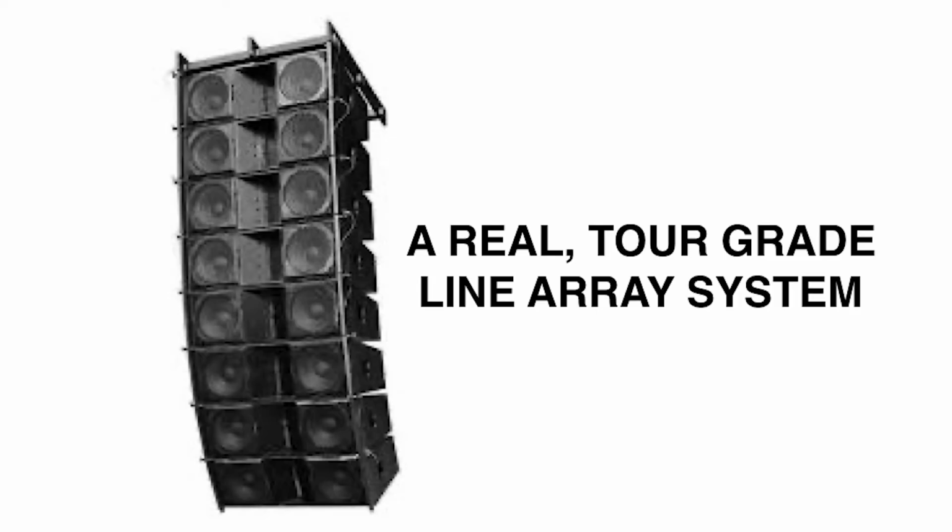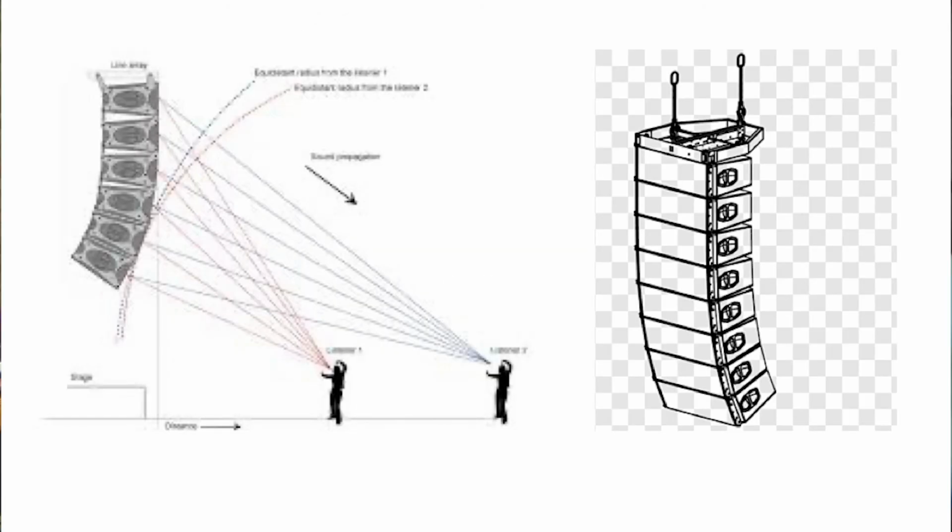The buzzword du jour in the industry these days is line array. This type of speaker arrangement is a line array. Basically, as it describes itself, it's an array of mechanically interconnected speakers hung in a vertical line. The idea is to control the coverage within the room by adjusting the splay or angle between cabinets, and adjust the coupling between the cabinets within the array by gain shading adjustments.